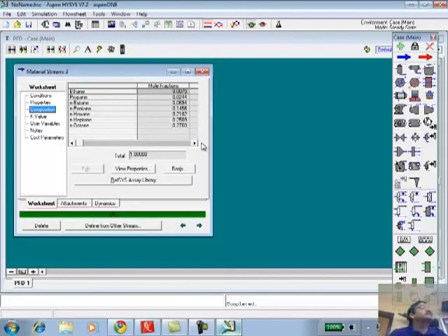What does this tell us? This tells us you cannot do that in one stage, and this is why you need multi-stage. Okay? In the multi-stage column, you can completely get rid of one component from the top product or the bottom product. Complete meaning 0.00001, almost trace amounts.